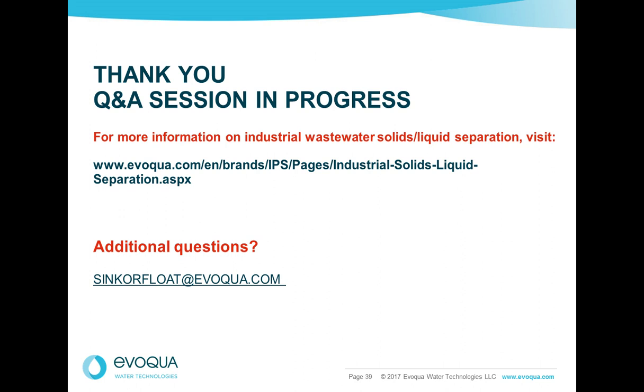But a lot of solids, even solids that you don't think will float, will. And if it's an application that requires a smaller footprint or a thicker, more concentrated solids, a DAF will typically produce solids anywhere in the 2 to 10% total solids range, which is going to be an order of magnitude higher than what you would get off a gravity clarifier.